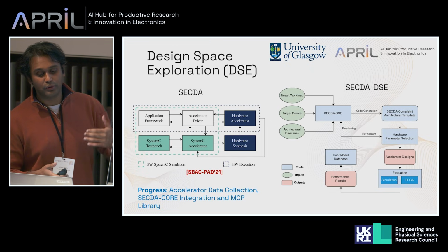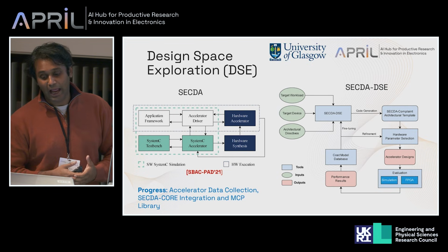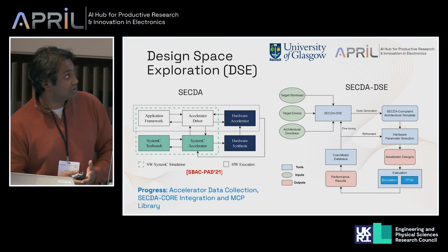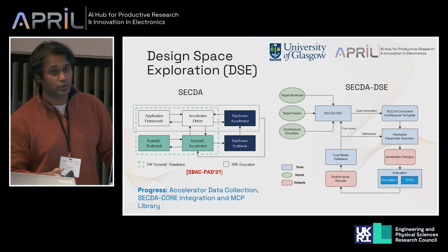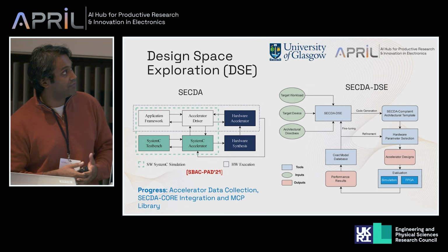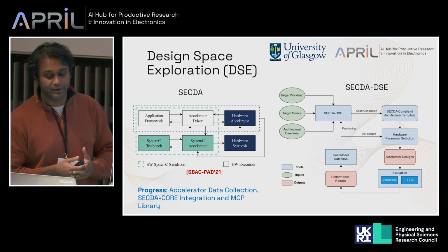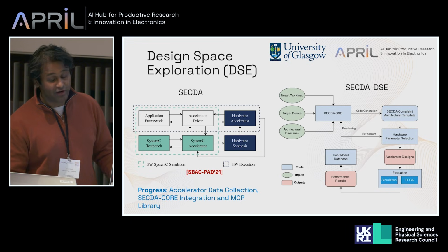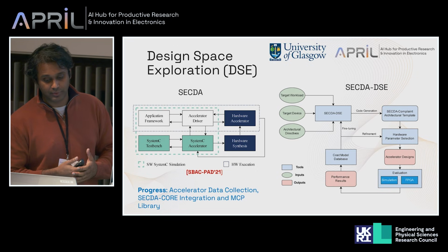This will allow you to get to a better quality of design much faster without ever having to use the FPGA and hardware synthesis. Ideally, we can also use the same hardware description in SystemC that we created through the simulation to do hardware synthesis without changing any of the code. So basically, you press one button and wait a while, and you will have a hardware bitstream that you can map onto your FPGA. With that, you can verify your performance and identify bottlenecks that weren't caught during the simulation.